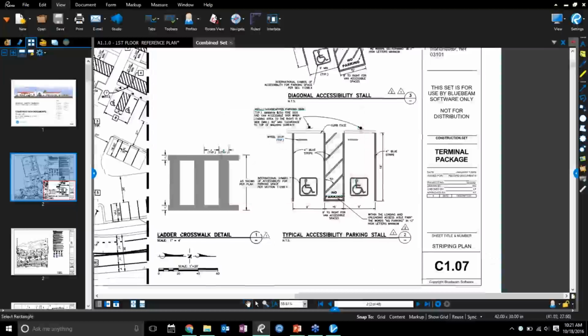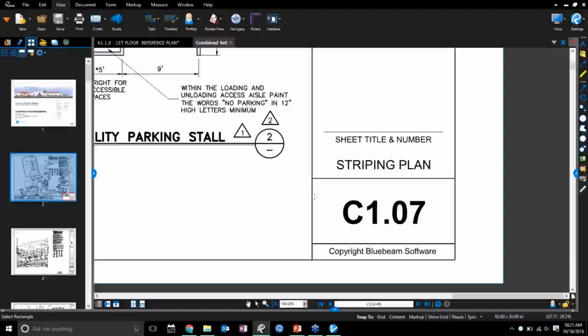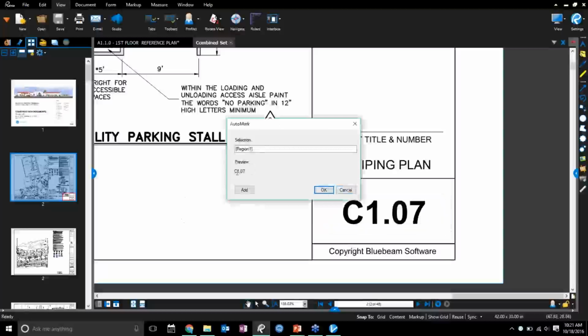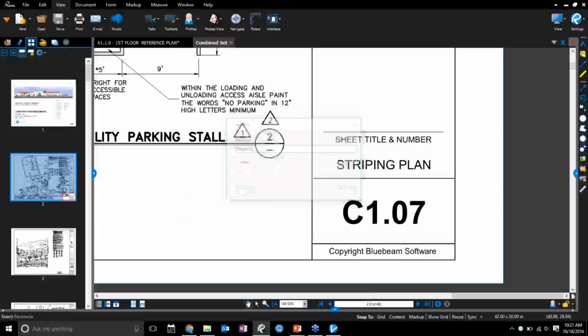So Page Region, go ahead and, in this case, I'm going to use the first criteria as my sheet number. This is a really important piece of information, as, for example, the first letter is the signifier of what discipline, the first number is the type of sheet, and so I want to know this offhand. I also want to add a second region for the sheet name itself.